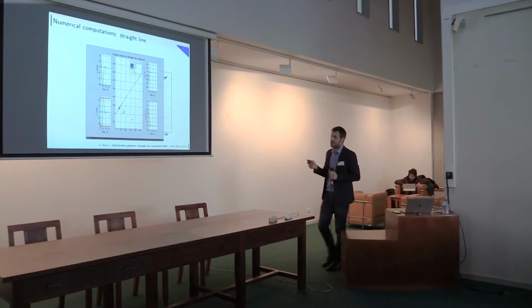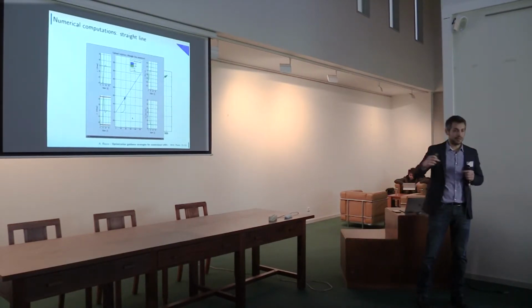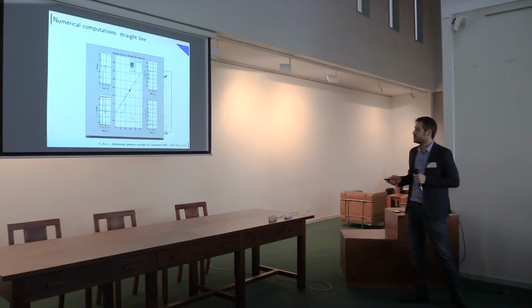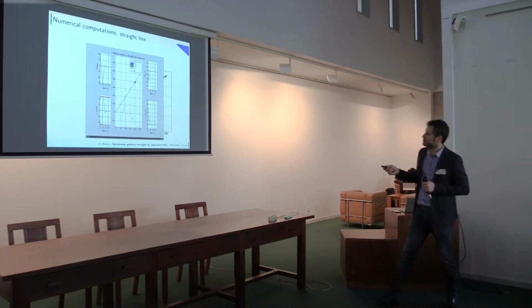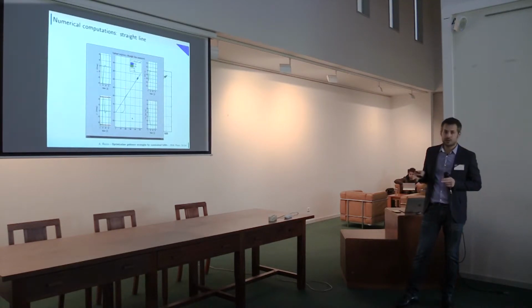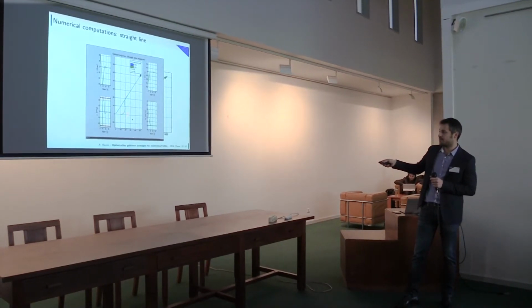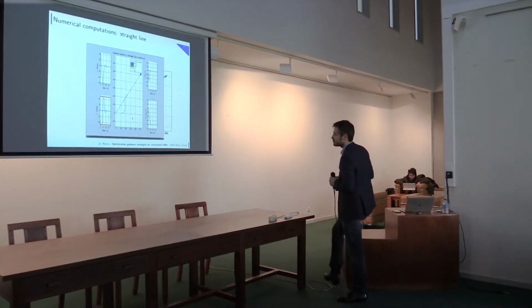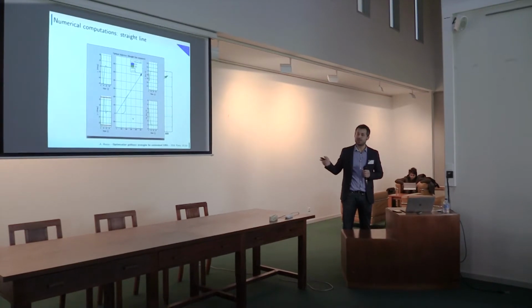Okay, a simple one. We have an initial condition for our UAV, and we want to follow a desired path with a given velocity attached to the path. The blue box is the virtual vehicle. What we can see here is that at the beginning the velocity decreases in order to turn. The UAV is able to have a smooth transition between the initial condition and the straight line path. The UAV reaches the maximum roll rate here, so it's aggressive for the roll angle and smooth for the airspeed.